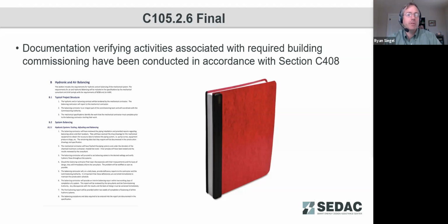Because of all the interactions, it's not uncommon during commissioning to find issues where some interaction occurred, and so an air handler is not turning off even when it goes to unoccupied mode. Things like that can really come out in the commissioning process, so don't shortchange it. It is likely commissioning that is leading to poor building performance and poor building operation for modern buildings.